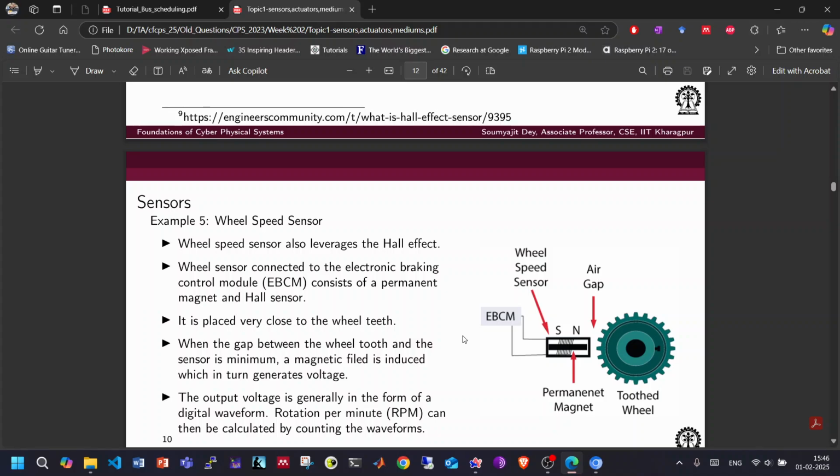So what I am trying to say is, when you are trying to measure velocity, the MEMS based, IMU based sensors are not very helpful. Those are helpful in measuring how much change in velocity there is. So the acceleration is very trustworthy data that we can get from there, but to measure velocity, we have to use something like a wheel speed sensor. We have to take the help of a wheel speed sensor.